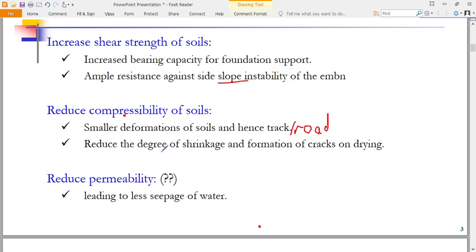Before compaction, you have water, air, and solid. Is that okay? So, the soil block after compaction: somehow you have reduced what? You have put in more particles, adding more soil blocks. You are reducing the air, but you can see that the water fraction remains. Therefore, you are increasing the dry density by adding more soil particles. These are soil particles. Is that okay? Adding more soil by expulsion of air, by application of a load.